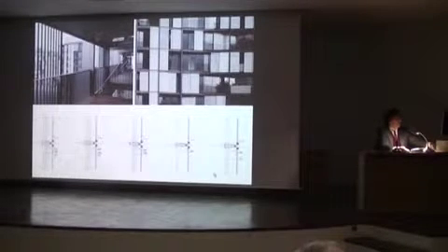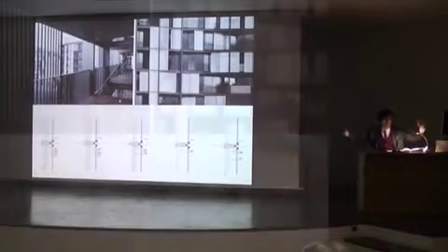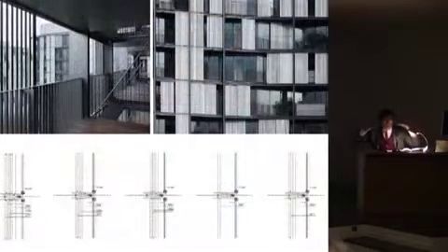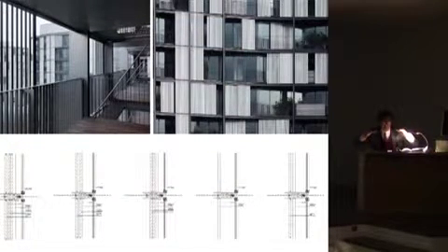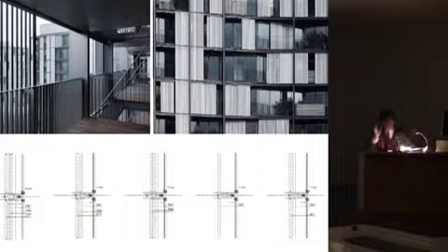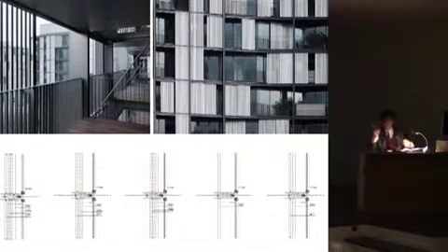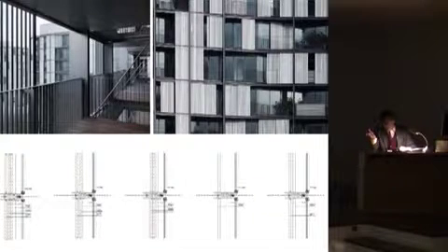Now it's working. So the terrace is bigger, and there you go, the window blind and the drain here. It's fantastic because you can't see it. You just don't see it, and water falls down from the terrace floor covering, but the drain collects it and takes it to the different pillars. And there are many drain pipes and very small. I advocate many drains but small.